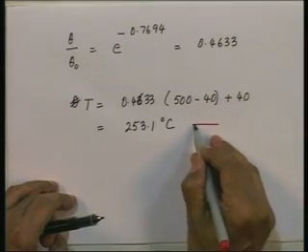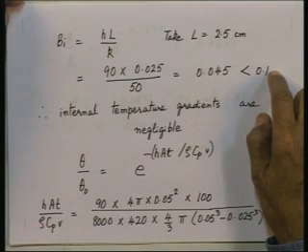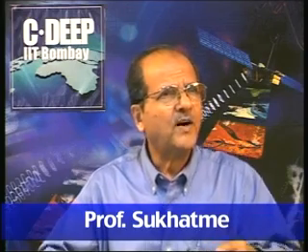All right. Now, this is the answer to the problem because we could neglect internal temperature gradients. If for instance, in this particular case, the data were such that the Biot number were more than 0.1, and you find yourself unable to neglect internal temperature gradients, then you can formulate the problem in terms of a partial differential equation in spherical coordinates. You will get boundary conditions, you will have an initial condition, and you will have to solve that partial differential equation with those given conditions, get a series solution. It can probably be done, but it will be far more complicated than what we have done by this method, when we have been able to neglect internal temperature gradients.